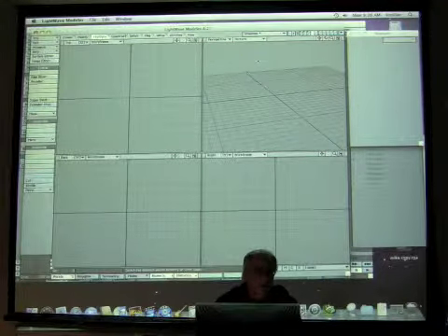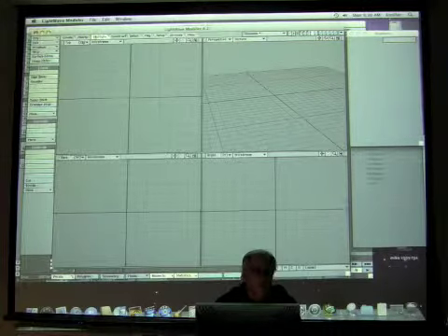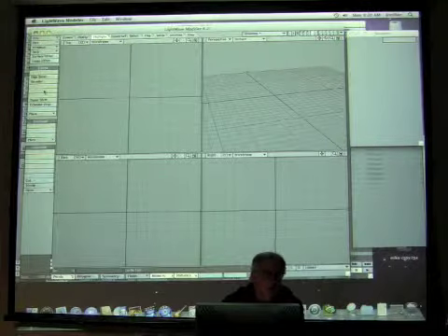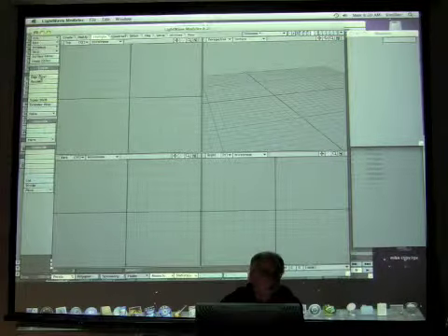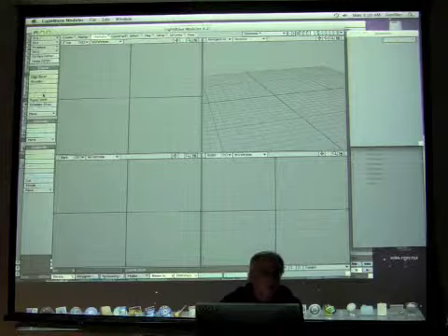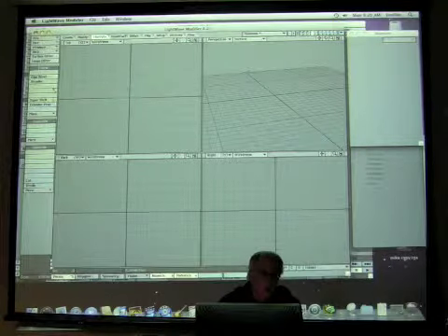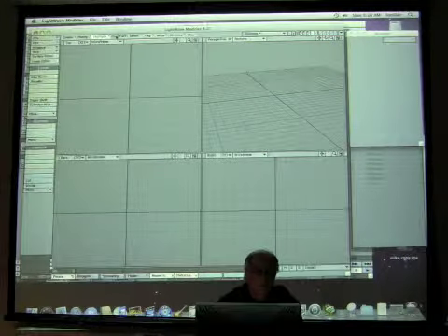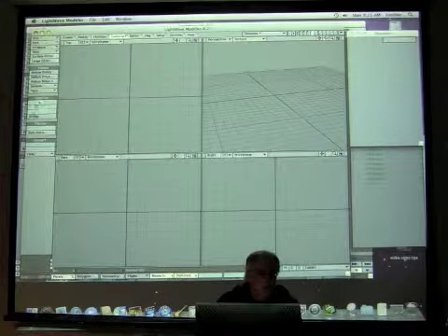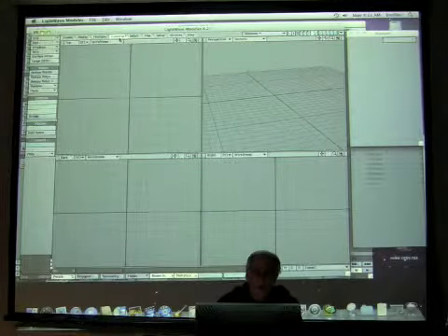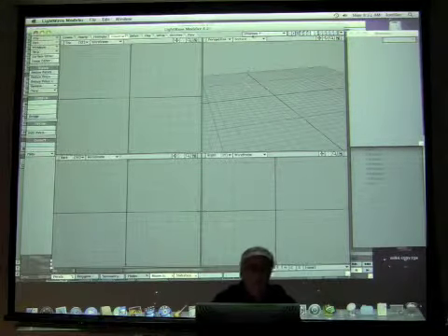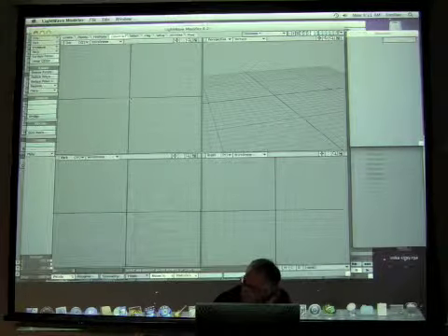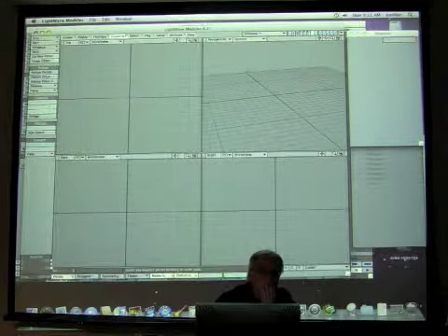Let's move on to Boolean. Okay, I just covered under Multiply the Extrude, and I covered Lathe. We've already used before Smooth Shift, and we used Bevel. So they all kind of fall into the same category. Now we're going to use under Construct Boolean, and you'll see that they are presently grayed out. To use most of the Boolean functions, you have to use two layers. So this is how you do it.